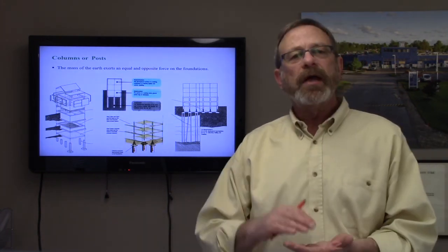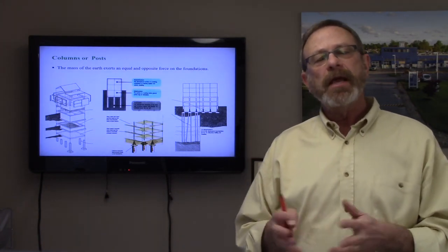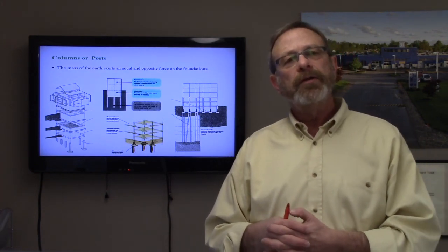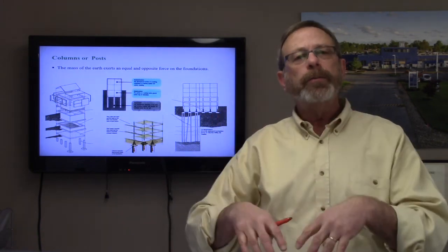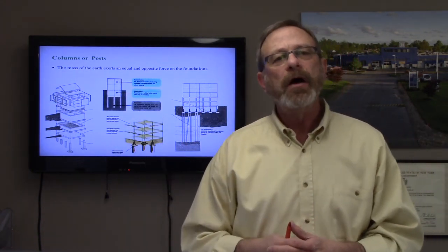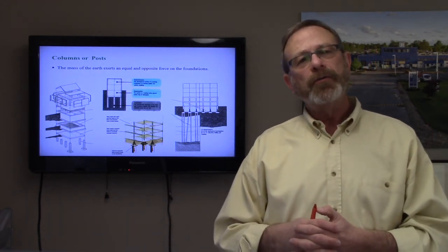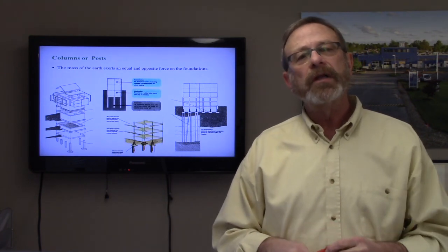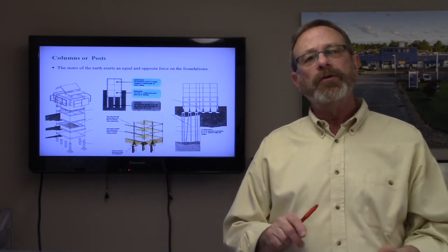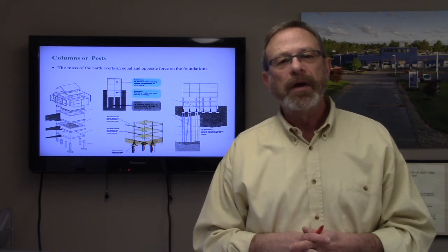So we discover that compacted earth generally by, again, taking soil samples. Maybe you take a backhoe, have your inspector, your soil scientist there on the job, looking to find out when there's no longer disturbed dirt, like fill that's been brought in from somewhere else, until you get down to undisturbed earth. And we want to also make sure that that's below 4 feet, because 4 feet is, in this area at least, the frost line, so there's no heaving and thawing of the earth below where the footings are. Otherwise we'll have the building going up and down seasonally perhaps.